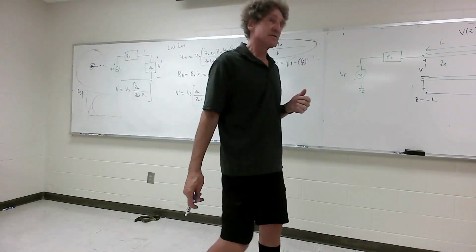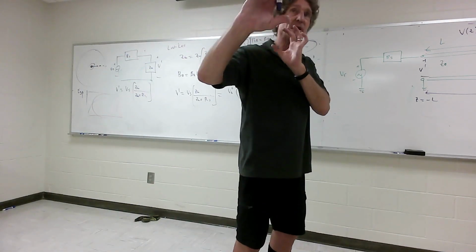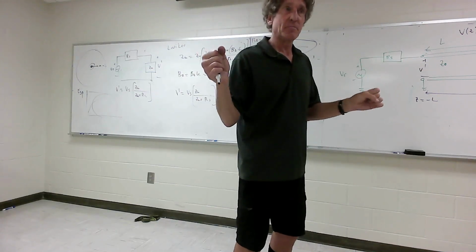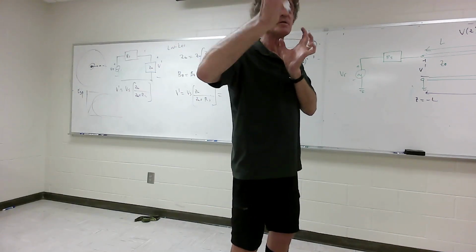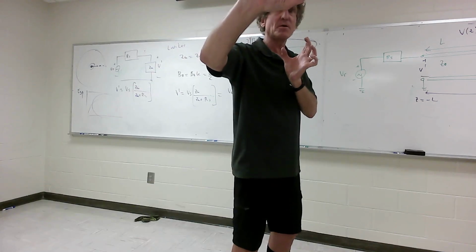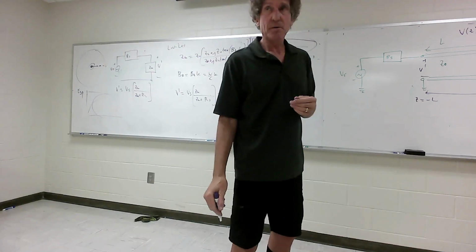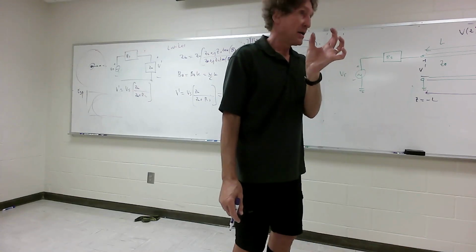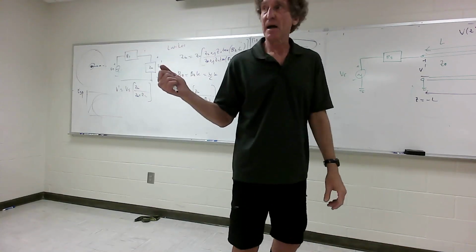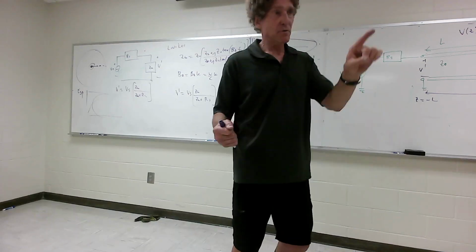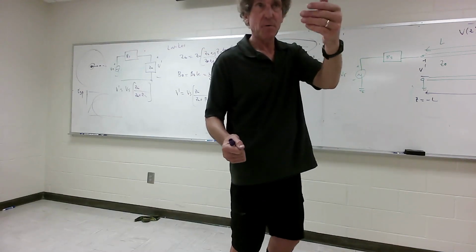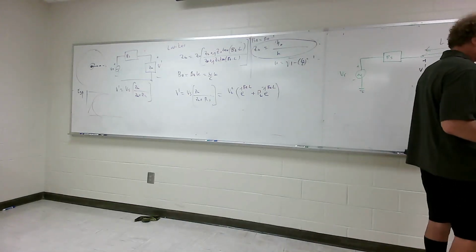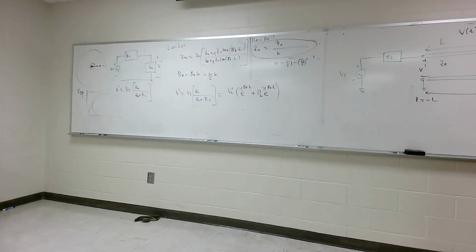Downside of working with waveguides is these are very rigid structures. Coaxial you can bend fairly easily. Waveguides, there's some flexibility and stuff like this, but they're harder to deal with. And typically speaking, the tolerances are much more exact. You can't have any variation. If you just take a hammer and whack a waveguide and put a big dent in it, you'll get what's called a hot spot and you get impedance mismatches, and it causes a lot of problems. So keep that in mind. Some of you will work with waveguides, almost guaranteed.